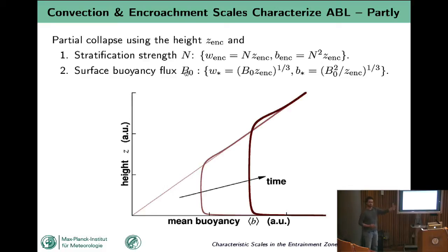And then you start to study this problem in the sense that you want to predict it in time, and one possible way to do that is you obtain the characteristic scales, and then in terms of these characteristic scales, you can normalize things, and you obtain some self-similar behavior, as we see in many different boundary layers. And here's where the problem starts, because you have different sets of characteristic scales. For, again, the height of the boundary layer, you can think of the following two possibilities.